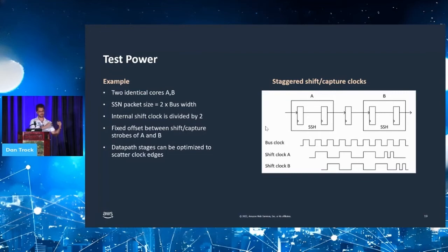This depends on the delay of the packet, how soon the packet will get from one core to another. In this case, core B will receive the packet 3 cycles later after core A, okay? And we deliberately put that small pipeline in between these 2 cores, and I will explain why.